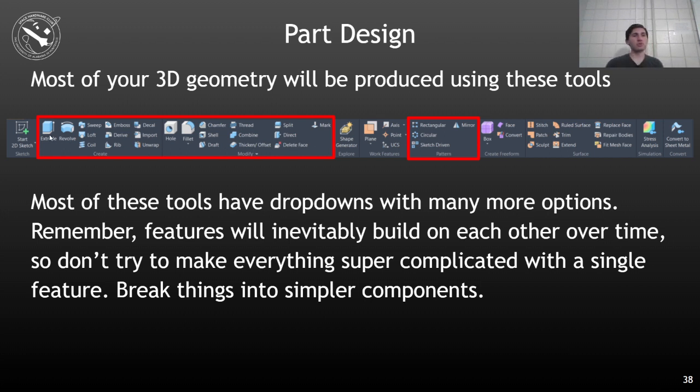So the way that Extrude works, you can kind of tell by how the icon is set up, where you have basically something, some profile, and you're extruding it in one direction a certain amount. Revolve, you can also tell by the graphic, you have some sort of profile and you're revolving it around, making some kind of curved or arced solid. There's a handful of other tools here. We won't deal with all of them. We'll deal with some of them.